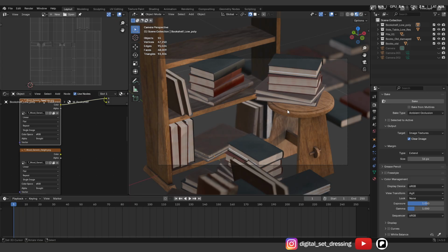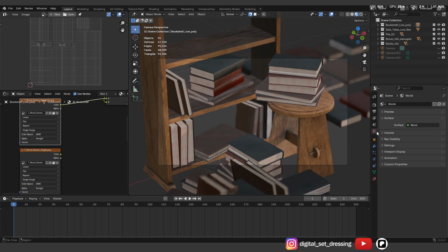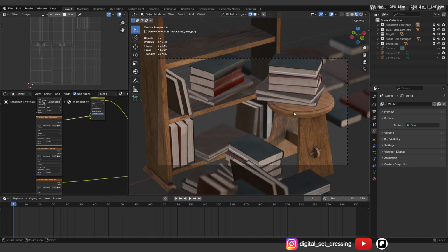To create a scene with so much contrast, it's sometimes good to not use an HDRI in the world setting. We're not going to do this because it creates too much global fill. So I'm going to talk you through setting up 2 spotlights.